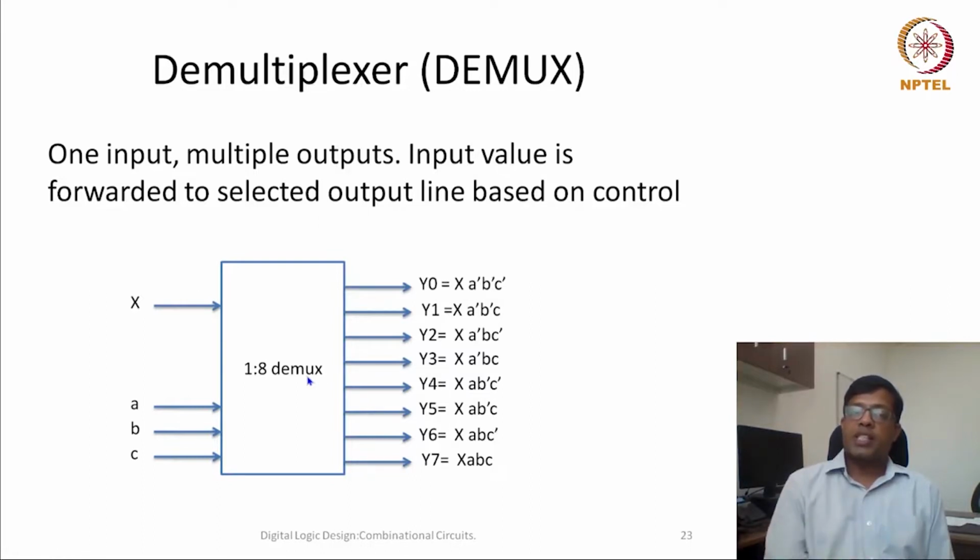Let's say x is a 4-bit input. In one of these demuxes, x0 is given as input, in another x1, then x2 and x3. So whenever we say a vectored or bus-based demultiplexer, in the circuit it would be implemented as replicated copies with different inputs, where each bit is given as input to one of these demuxes. So this is how these demultiplexers can be designed and utilized.